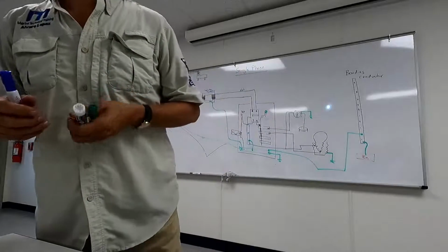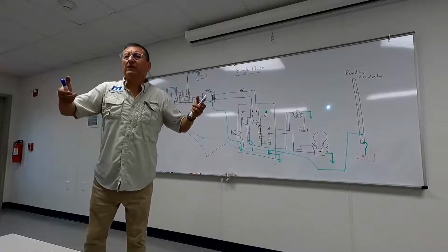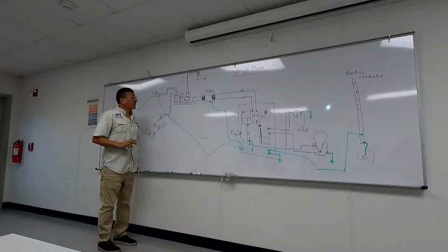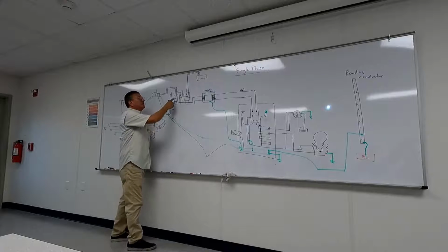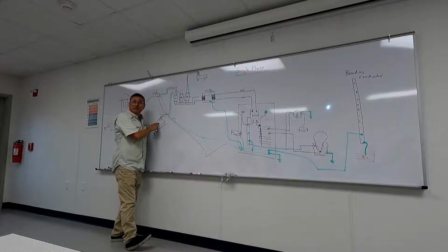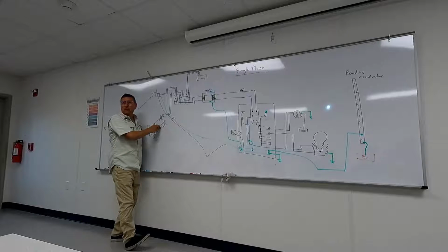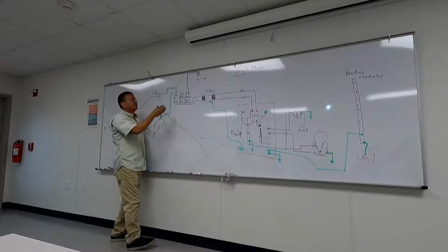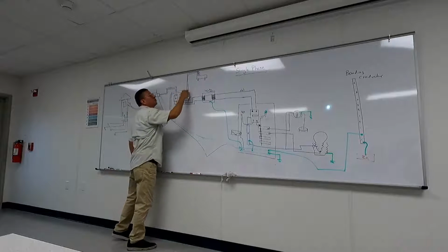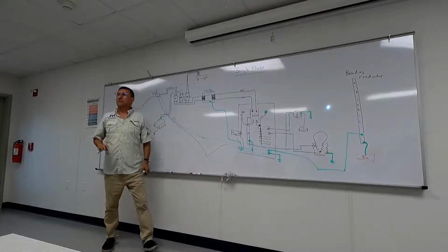You overheat the wires. That's the problem. But if you have, for example, this and this together, you probably send power into the inverter and you damage the inverter. You send power coming in through the output and you damage the circuit board. Or vice versa. If the generator is off and you have this and this on, you send double power through those cables and you damage the winding of the stator. That's not good.